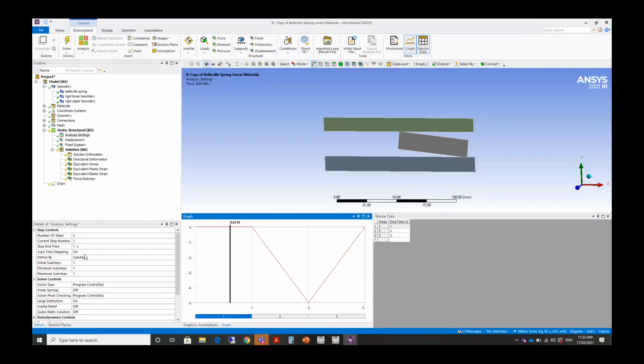All right, so with my initial sub-steps, what were we, 2000 MPa. We need at least a tenth. So I'd say 20 initial sub-steps and say 5 minimum, and I'll make this 40. So if it struggles to converge, it can bisect.